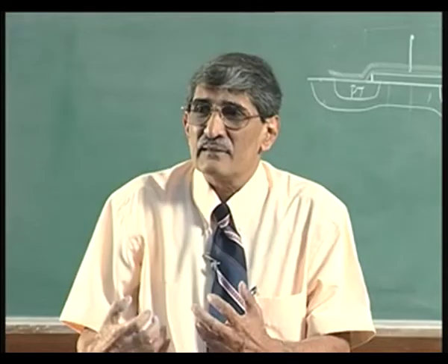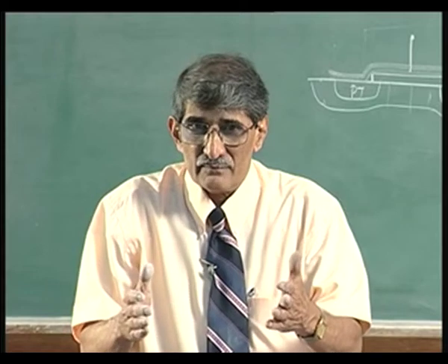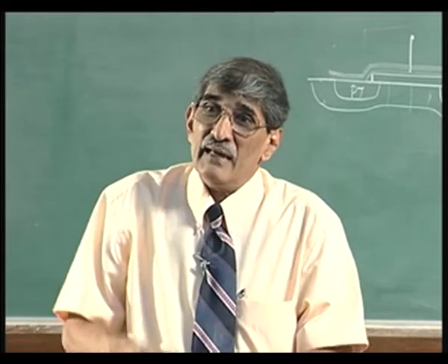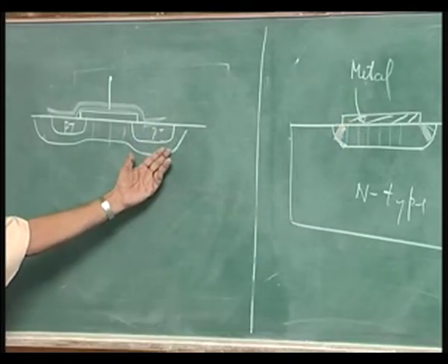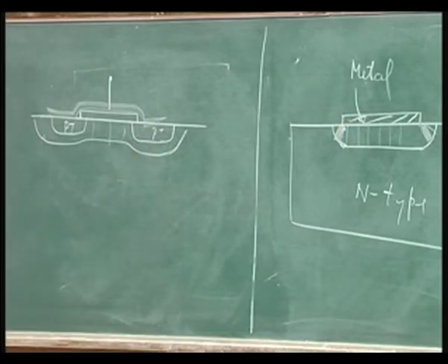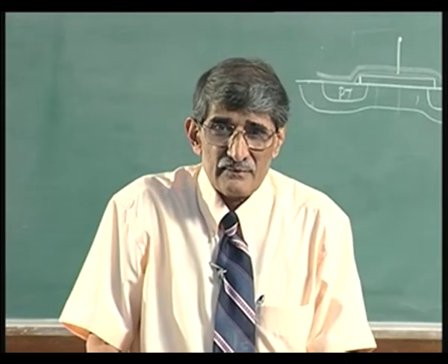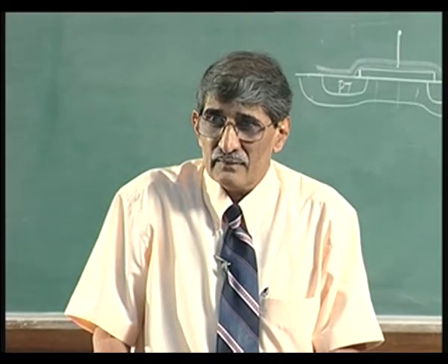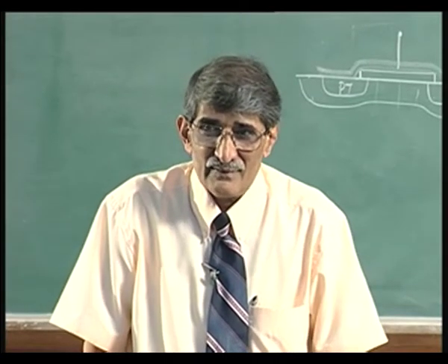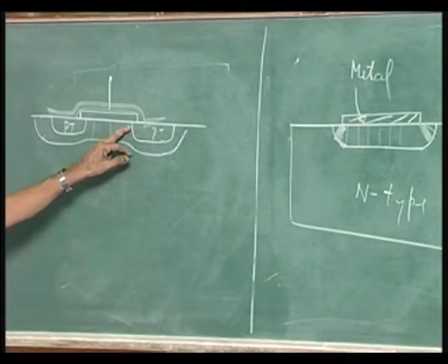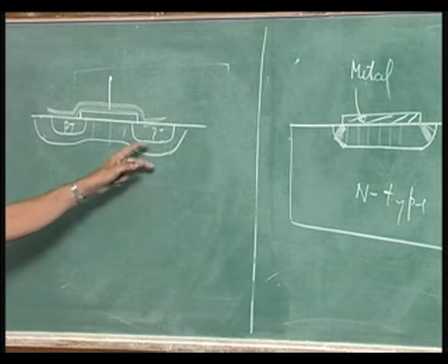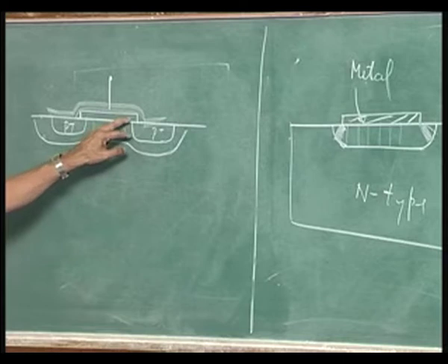So, you do not have the increase in the reverse current in that portion, in the Schottky diode portion, but you will say there is a crowding effect coming up here, but now it is a crowding effect in the p-n junction. The leakage currents in the p-n junction are much smaller than those of the Schottky diode. So, you have shifted the crowding effect from the Schottky barrier to the p-n junction, and in the p-n junction, even if the field is higher, leakage currents are much smaller.